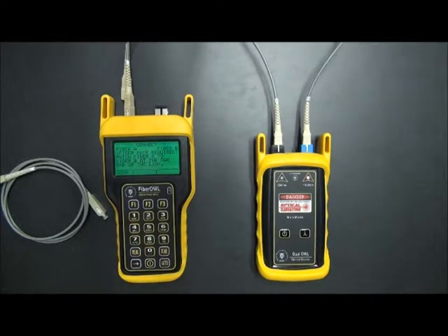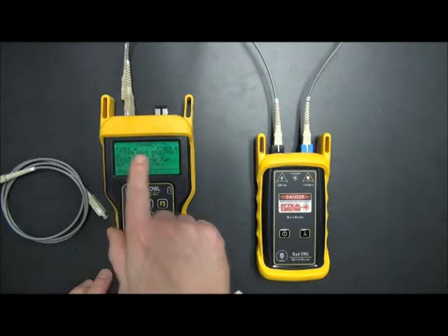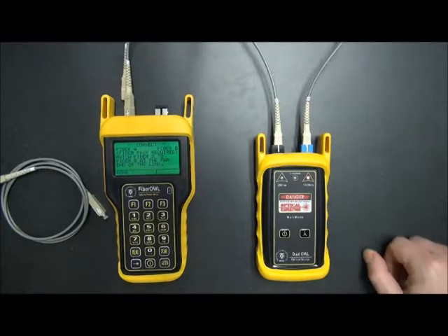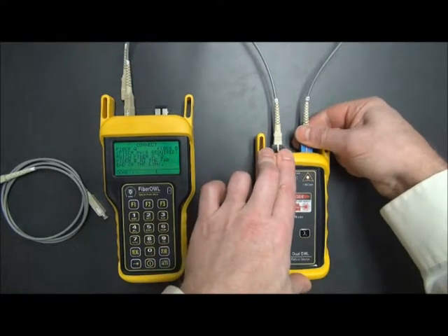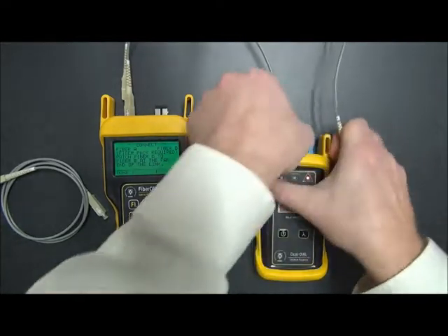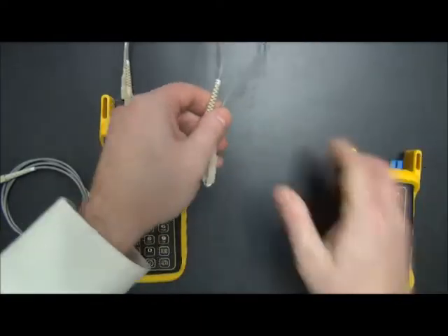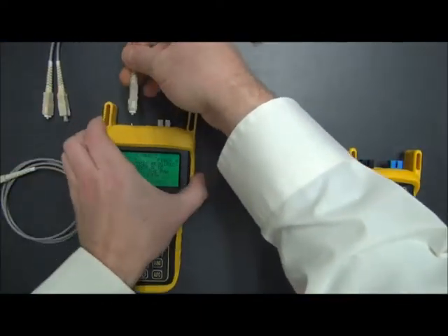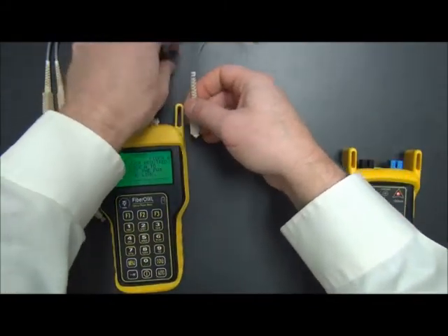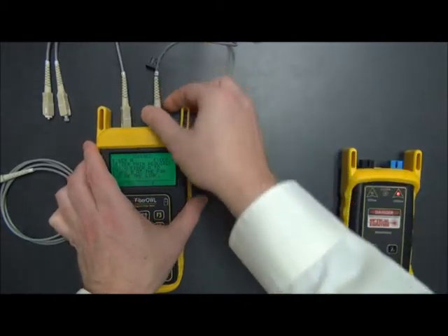Okay, and then the next screen here describes how you're supposed to connect the tester to the link in order to take the length measurement. Now, as you can see, you need fiber A and fiber B, a fiber pair required. So you need 2 fibers plugged into your link. And we're just going to use the duplex cable that we have here, use this as part of the fiber link. We're going to plug those in. So now we have a cable attached to the transmit port and the receive port.